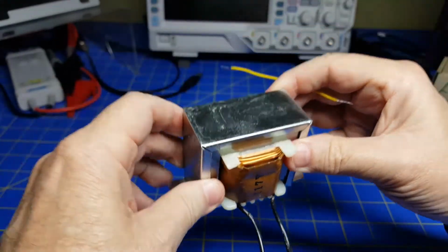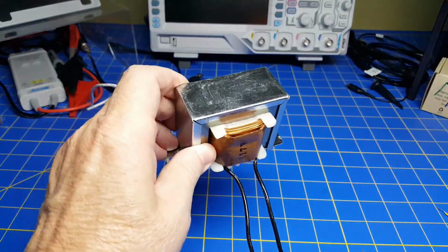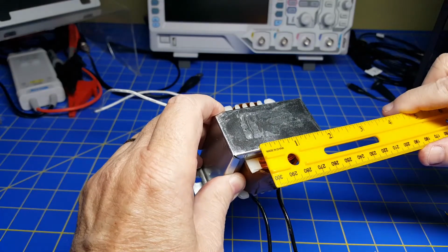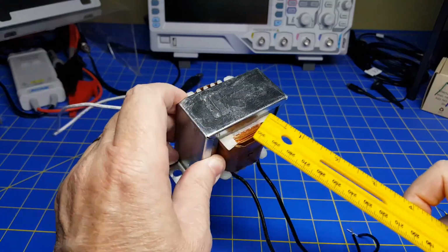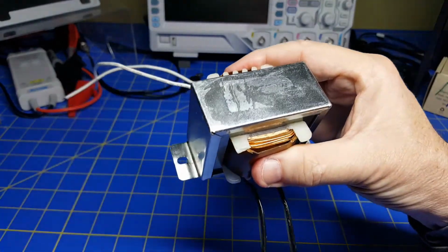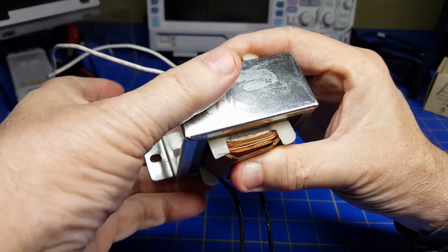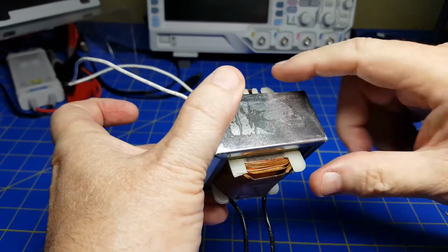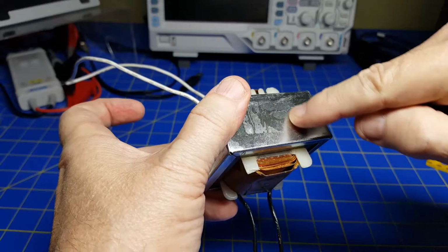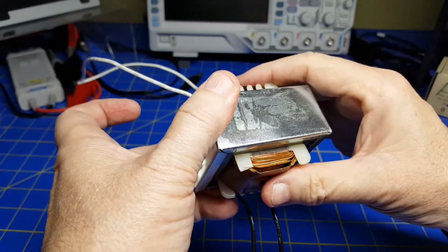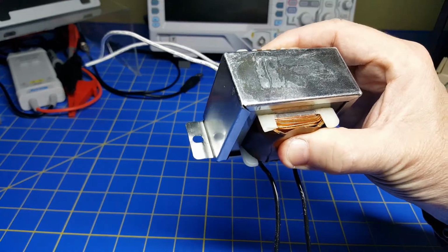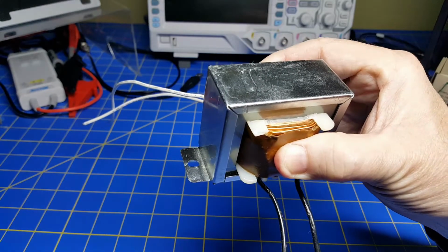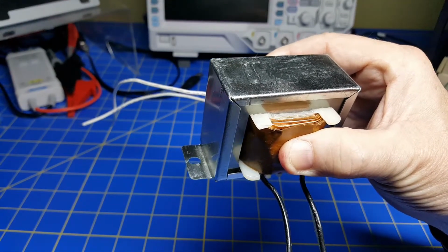We also can figure out dimensions. So I've got these wires, and if I put up my ruler, it looks to be maybe a 1 inch by 1 inch iron core that these wires are wrapped around. So 1 inch by 1 inch means that each winding or each turn of this wire is going 1 inch, 1 inch, 1 inch, 1 inch. So it's probably about 4 inches of wire for each turn. So using that information, we can start to do a little detective work to figure out how much resistance the wire would have and maybe some of the other parameters.